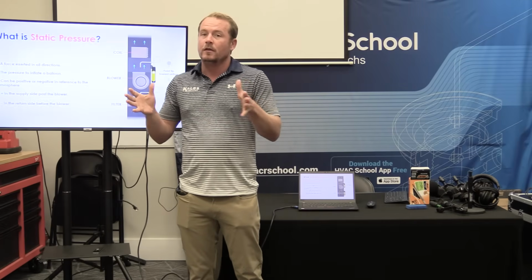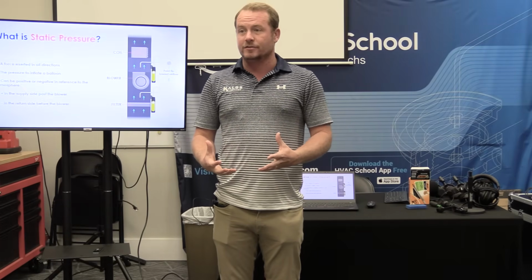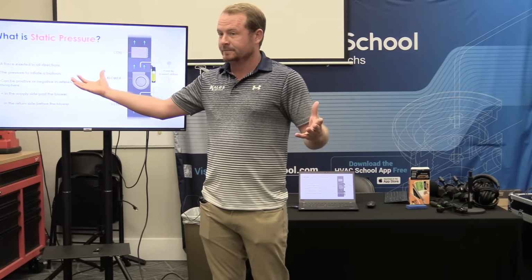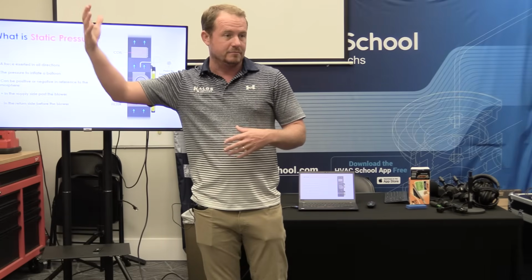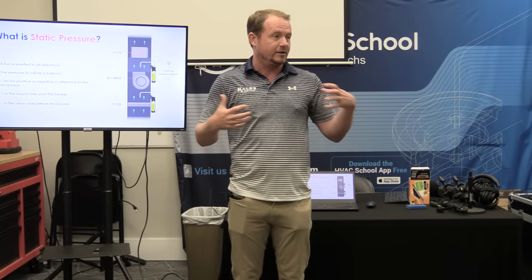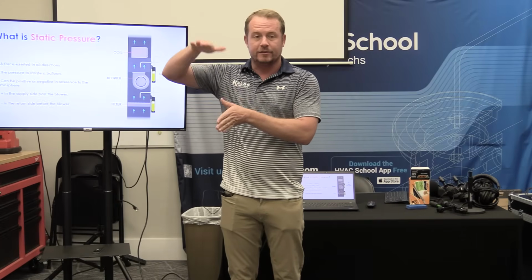Okay, so here's an example. I would create positive static pressure in this room if I put a fan in the door and blocked off the door and blew air into the room, right? And why would that create positive pressure in this room? Because it's forcing air inside from somewhere else, right? So we're taking air, which is just molecules, and forcing them into the room from somewhere else, and so those are exerting a force in all directions on the room, right? And what happens if I turn the fan around, seal the door off, and blow air out of the room? What happens to the room? Negative pressure. It goes into negative pressure, right?